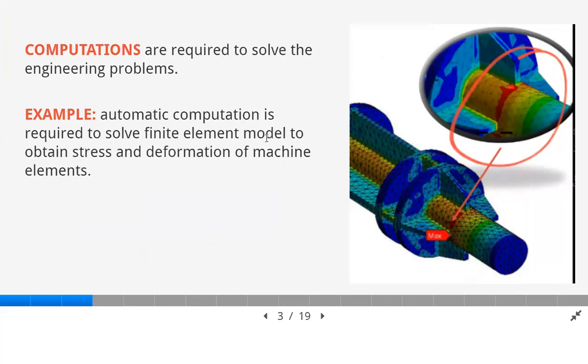The temperature is about 400 degrees, so it will affect the behavior of the material. We cannot model our object here using linear material or linear deformation. And we also cannot use the tensile test data because it doesn't contain the effect of temperature.